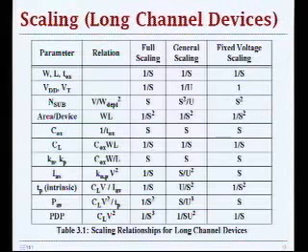But with the realization of this power problem, people were forced to scale the supply voltages down and adopt new standards for supply voltages. And that's why you had 5 volts for a very long period of time, then 3.3, 2.5, and so on. Now the question is, if you have a velocity saturation problem, why do you keep supply voltage that high?